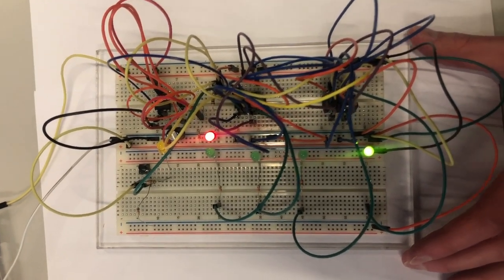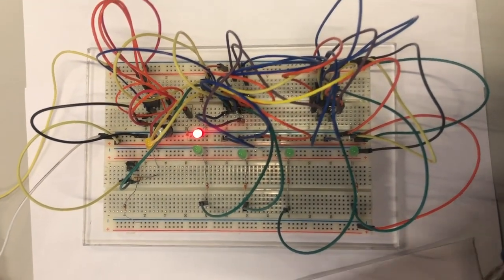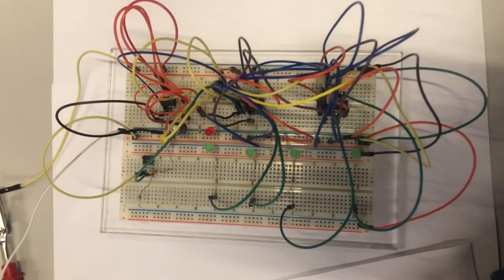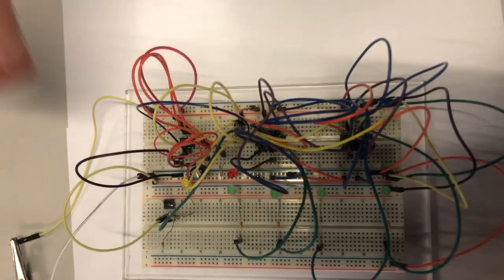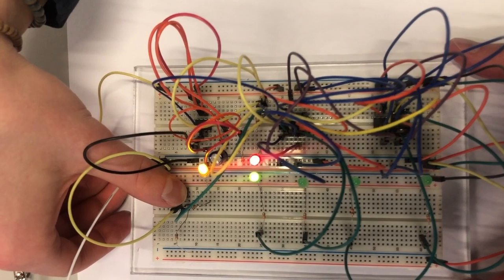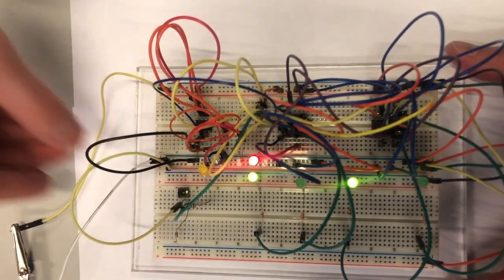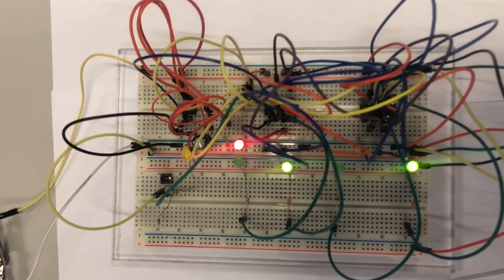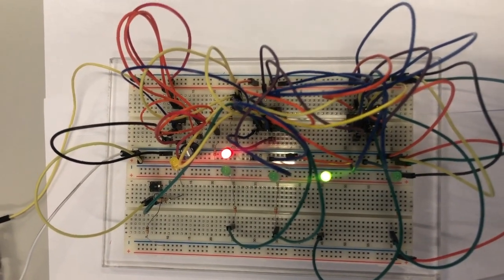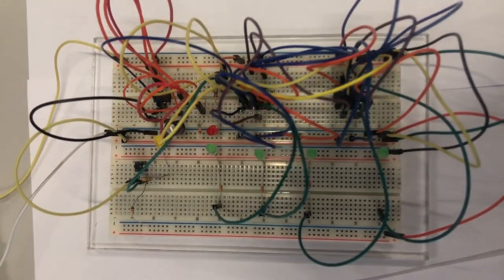When we push the button for 2 clock pulses with 1 gap in between, first 1 clock pulse, paused and then pushed for another clock pulse, this led to a gap between the LEDs, which can be expected because when you push the button for a clock pulse, the values from the input are stored in flip-flop memory state. Then each flip-flop stage triggers the transfer of each bit to the next flip-flop stage.